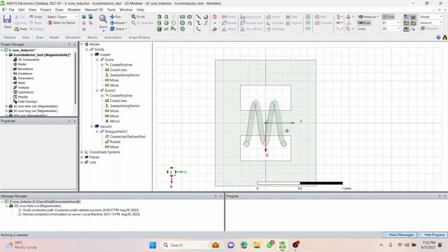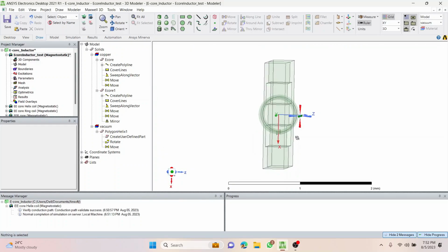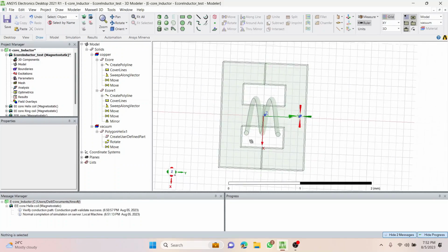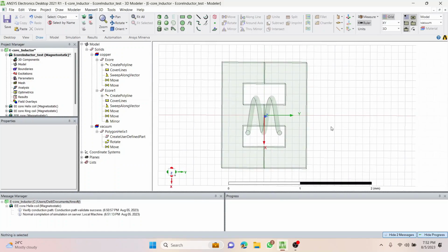And I'm looking at this now. Yeah, this looks good. Sadly, there are just 2 turns, but I think we can work it pretty fine. Okay. Now, if you want more number of turns, what we can do is reduce the polygon, the dia, or the radius, and then reduce the pitch as well. The pitch means this gap between the coils, between the turns.